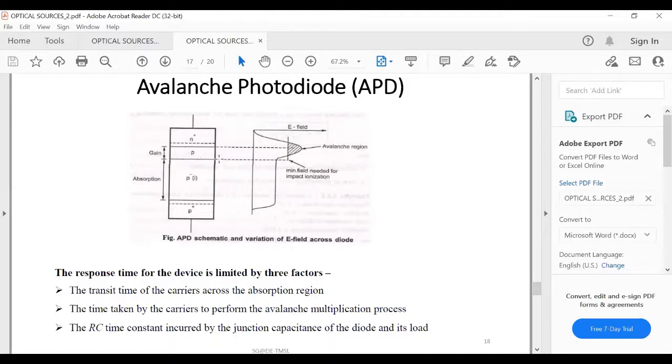Now under normal operating bias, this P region is completely depleted, and that is known as the reach through condition. That's why these avalanche photodiodes are also known as reach through avalanche photodiodes. Similar to the pin photodiode, light absorption in this APD is most efficient in this position.